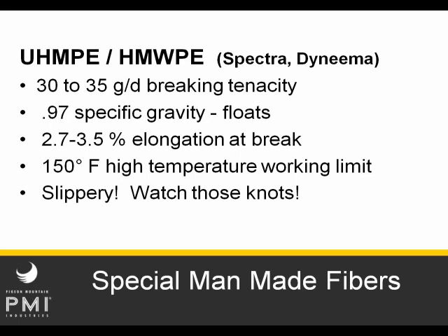However, again, there's very little elongation at break in these ropes, so you have to be very, very careful when using these ropes because they transmit the force of a fall or of a load directly to the anchor and directly to the user without absorbing any of the force within the rope. They also have a very low high-temperature working limit, and as I mentioned earlier, they're very slippery and don't hold knots very well at all.